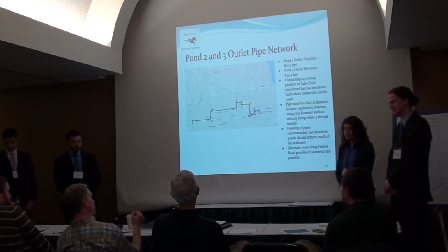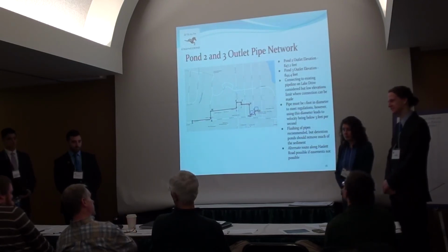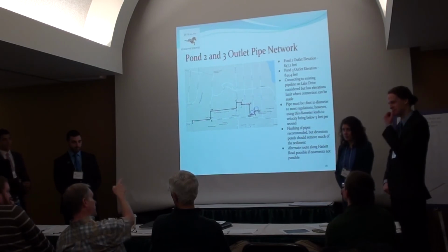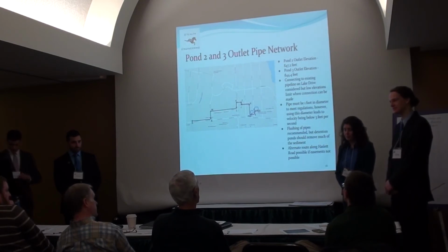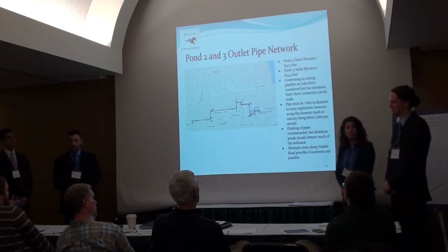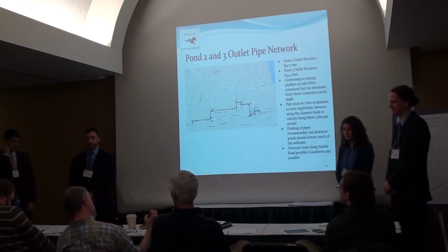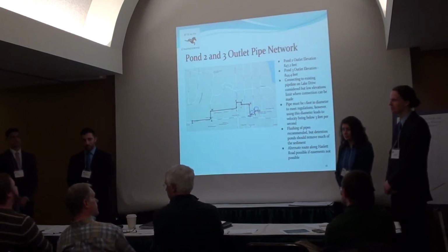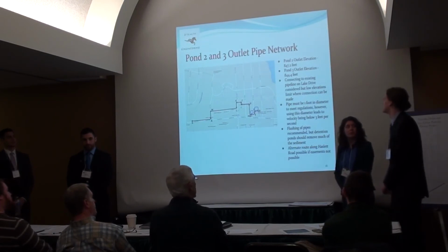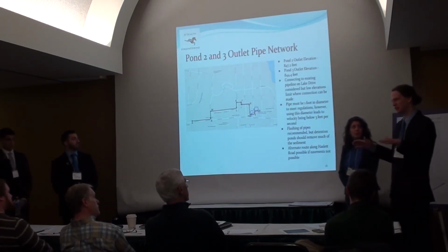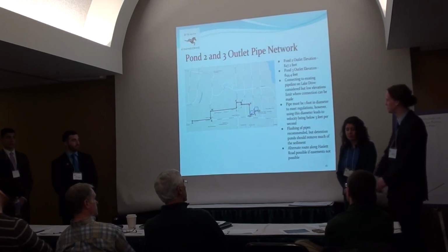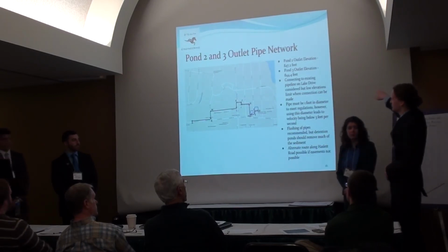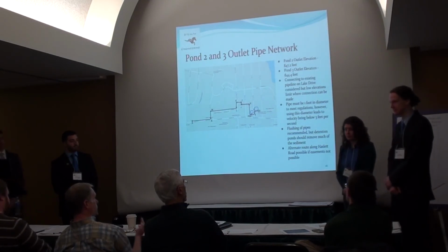Very low flow rate coming out. Is it possible that you may have water from the primary outlet drain backing up through your outlet system and therefore not be able to actually do outflow without sufficient force to push its way out? Based on the ponds being full and then outflowing, there should be some force backwards. I don't know if the water would have enough force from the under-gear flood to rush all the way back up the pipes. You think it's worth considering? Yes.